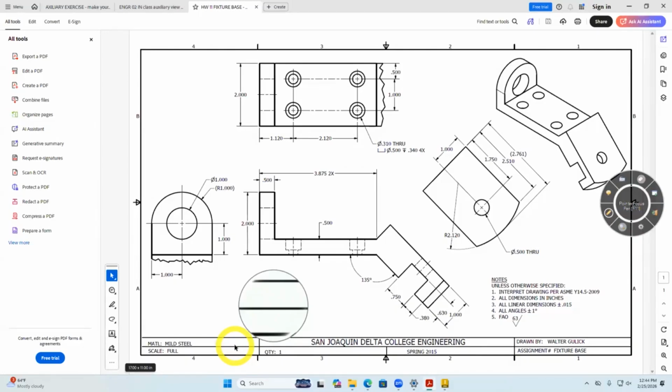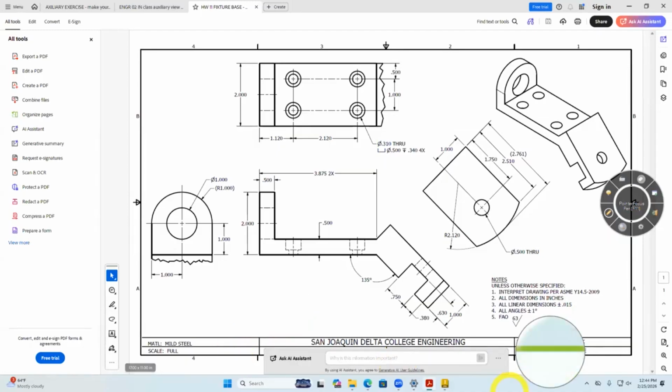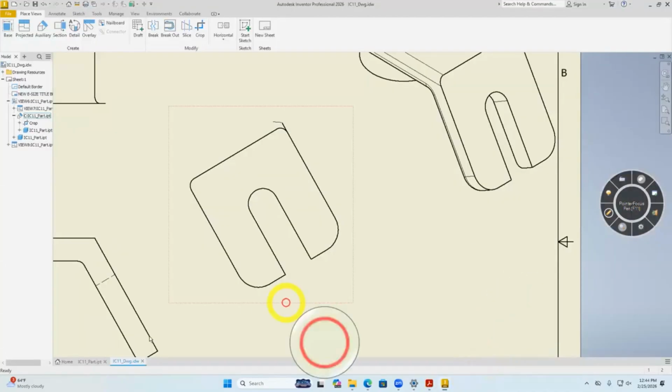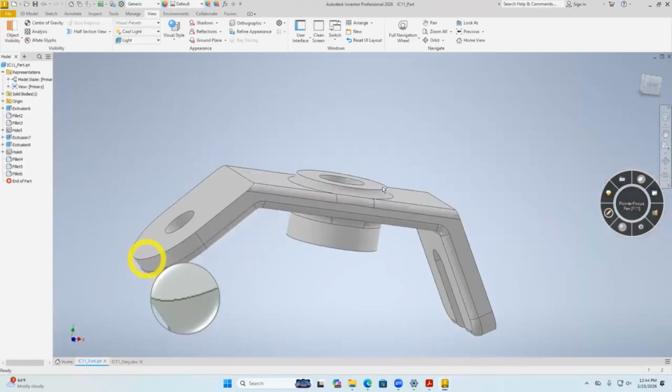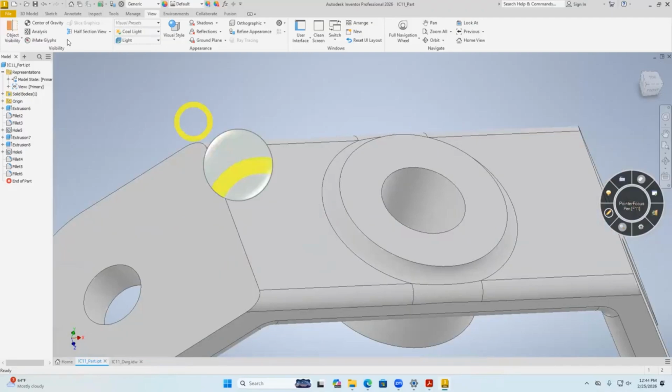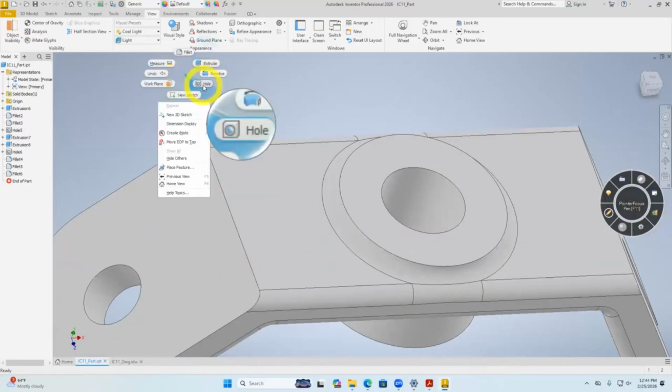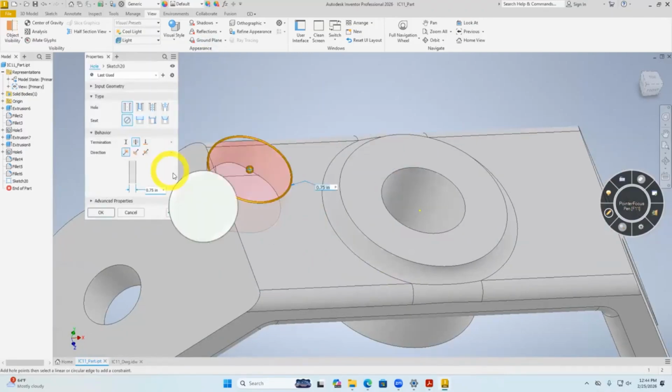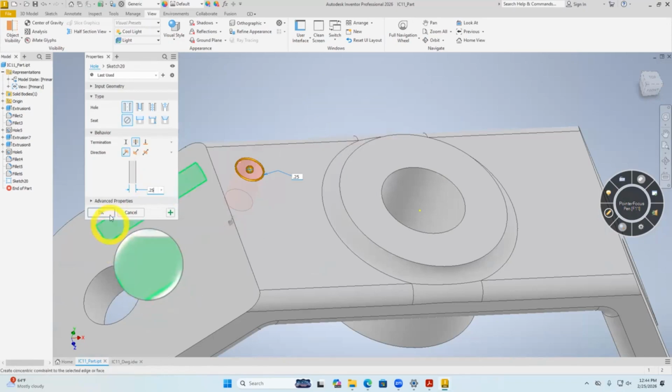We might want to talk about hole patterns. I don't think I told you guys about it, right? The way you do a hole pattern is like this. You come over here and you select, let's say that I want to make a hole. So I'll make a hole. I'm going to make a hole right there, okay? And I'm going to make it smaller so you can see the pattern. Let's say that hole is a 1/4 inch, okay? So first make a hole.